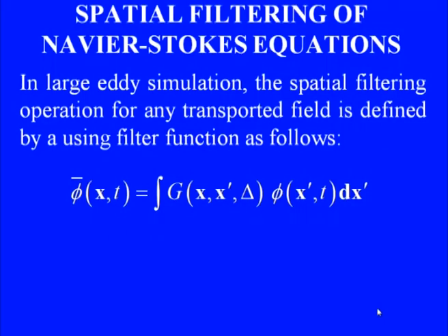And since the integration scheme is explicit, with a time step small enough to satisfy the stability requirements, we can calculate very efficiently our velocity components using this explicit time integration scheme. Now, let us have a look at the filtering operation in the Navier-Stokes equation.